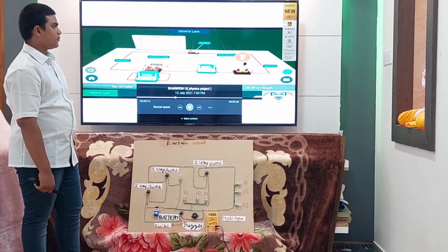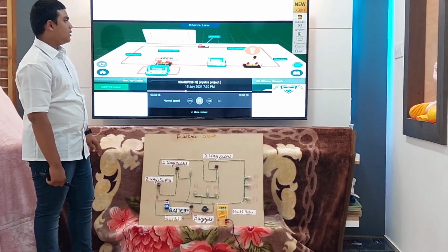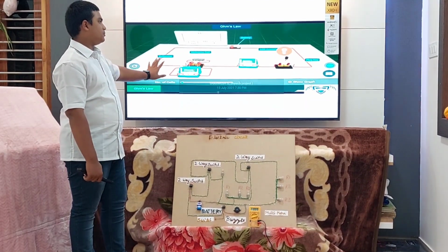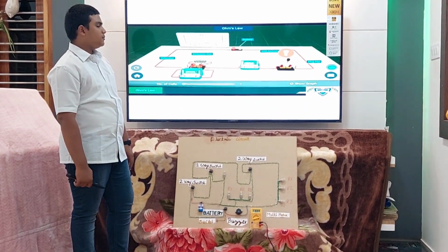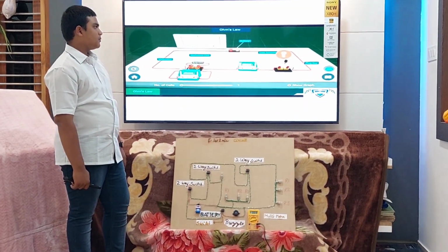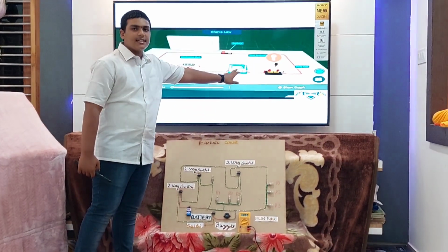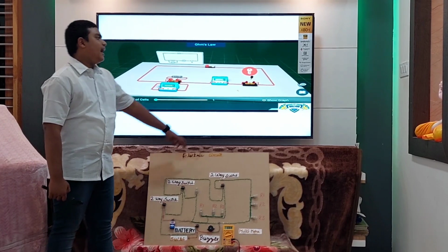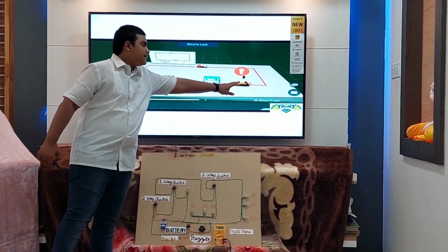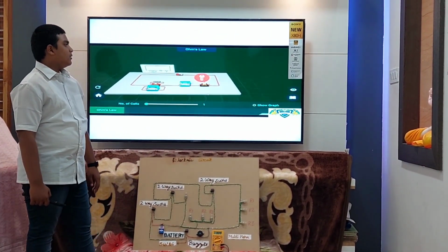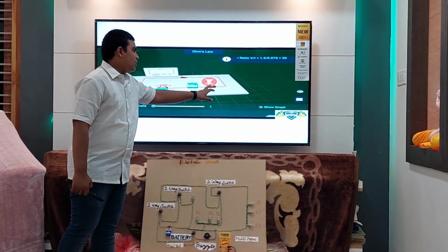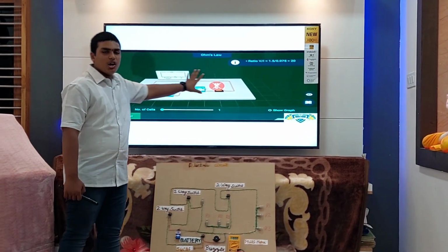We want to find the potential difference across this conductor. To find the current flowing through the conductor, an ammeter is connected in series with it. A cell and the ammeter are connected in series. Close the circuit by inserting the plug key, which is nothing but a switch. Current starts to flow through the circuit. When we plug it in, the voltmeter starts showing the potential difference across the circuit.